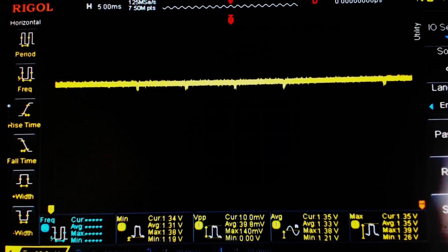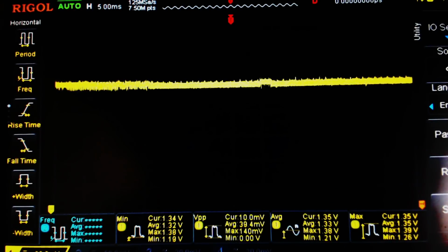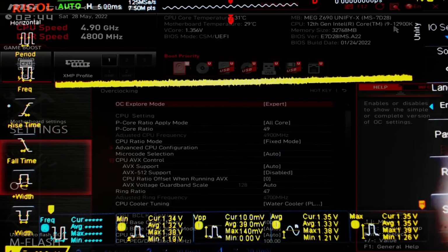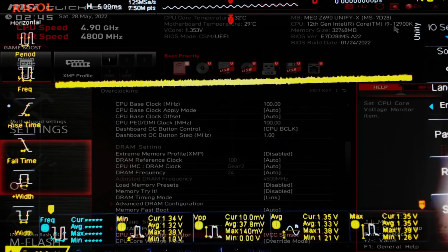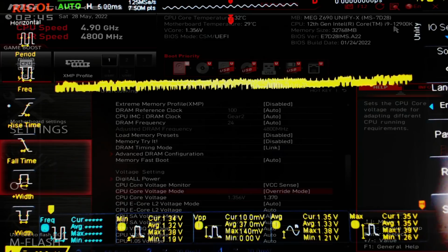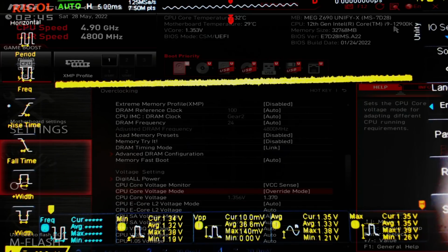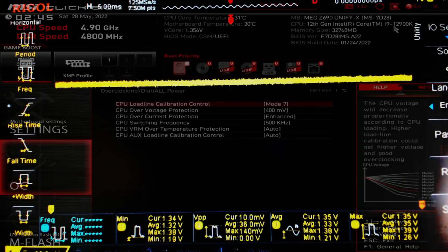The one concern I have making that statement is I'm not sure how comparable the measurements from the Torpedo are to the Unify X, right? These are completely different boards, completely different VRMs. This is an 8-layer PCB, the Torpedo is a 6-layer PCB, so it's entirely possible that this board actually lets a lot more noise to the back of the PCB where I'm taking my measurement than the Torpedo does, just because the PCB has less impedance to everywhere, which would actually be good because you have capacitors on the back of the board that are supposed to help with filtering the power delivery for the CPU.